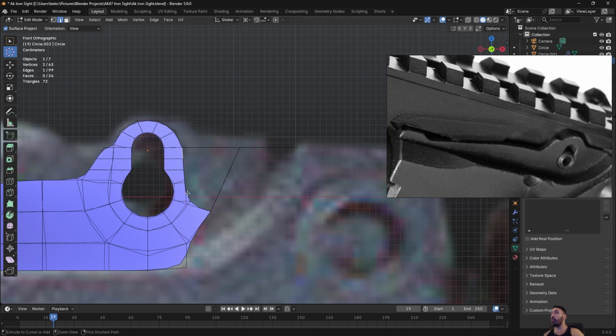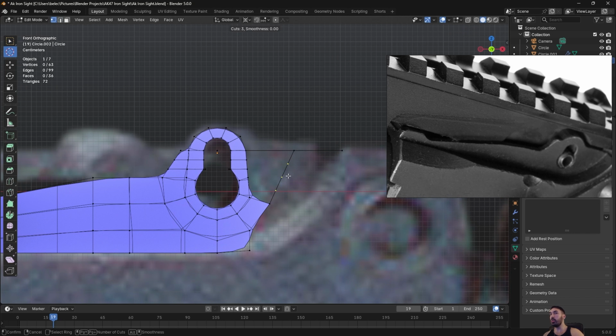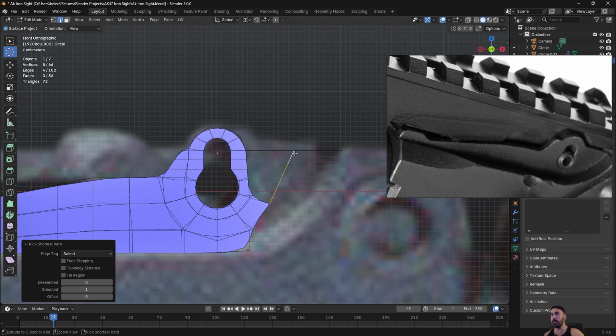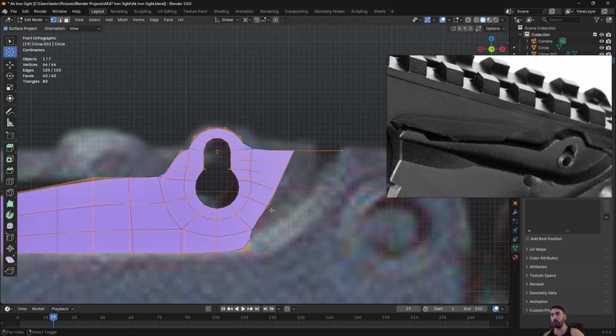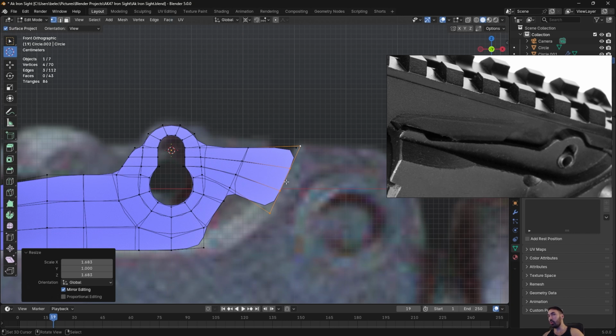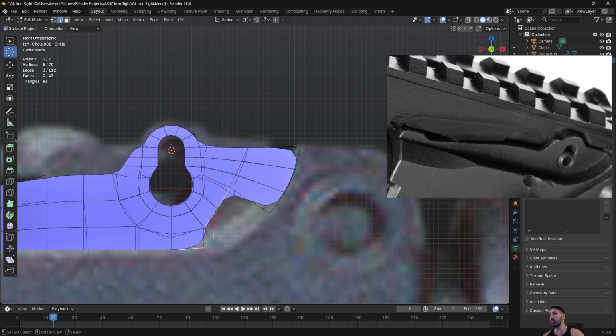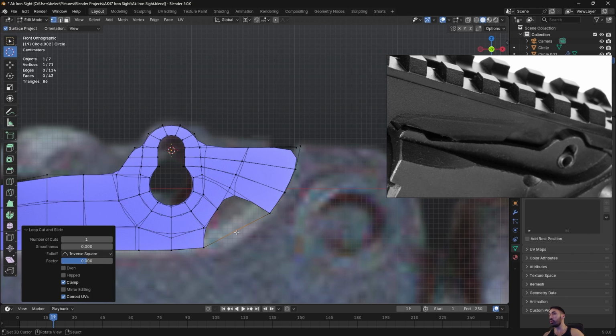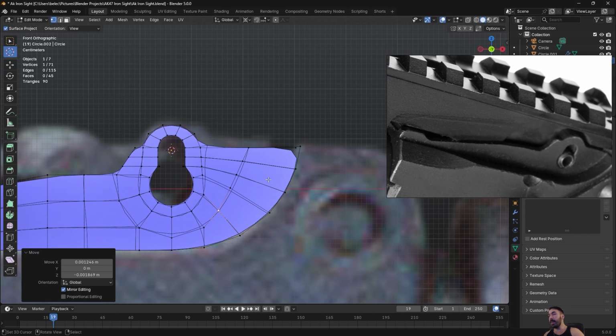Now we have these 4 edges over here which we have to connect into this edge, which are also going to connect into this quarter pipe. But if we add 3 new vertices over here, that gives us 4 edges, and then we have 4 edges up here at the top, and that's also not bad, because if we extrude these outwards like this towards the quarter pipe, now we have 1, 2, 3, 4, 5, 6 edges in the quarter pipe, which means the full circle would have a total of 24 edges, and that's a pretty nice number.